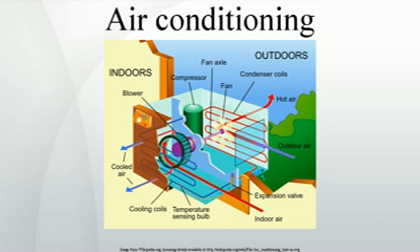Unlike a regular air conditioner, a dehumidifier will actually heat a room just as an electric heater that draws the same amount of power, watts, as the dehumidifier would. A regular air conditioner transfers energy out of the room by means of the condenser coil, which is outside the room, outdoors. That is, the room can be considered a thermodynamic system from which energy is transferred to the external environment.